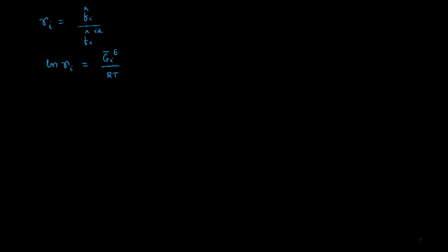Moreover, because of the summability relation, the total excess Gibbs free energy of the solution, G^E over RT, is sigma x_i G_i bar E over RT, and because G_i bar E over RT is related to the activity coefficient, this equation will become sigma x_i ln gamma_i.